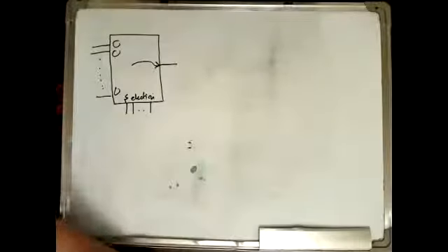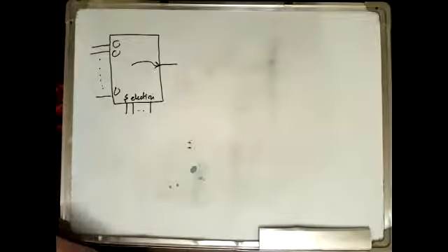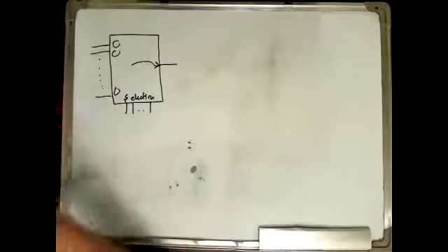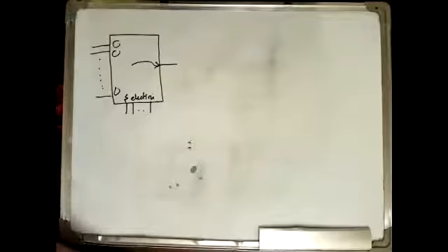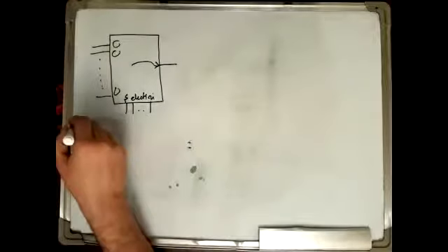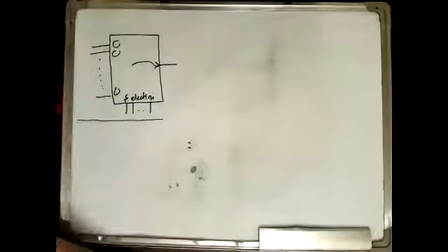and we started from the smallest MUX, which is the 2-to-1. We designed it the conventional way. Then we designed bigger multiplexers in two approaches. The first approach was by noting what is inside the 2-to-1 MUX, which is a 1-to-2 decoder, 2 AND gates, and 1 OR gate, if you remember. The other one was building big multiplexers using smaller ones. So that's what we discussed in the first lecture on the multiplexer.